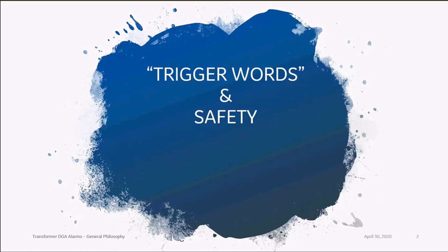So today I wanted to start out with trigger words, that's what I call them. When you hear things like, I think it's dead, or I think it's been de-energized, that to me is a trigger word. I need not only for somebody to be absolutely positive about whether or not something's de-energized, I also need them to show me how it was de-energized. And I'm sure you feel the same way.